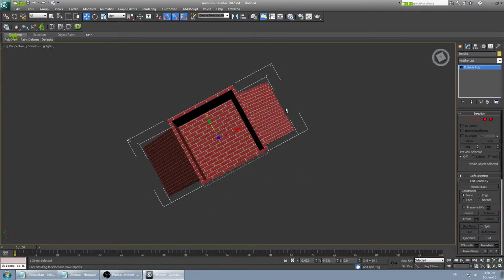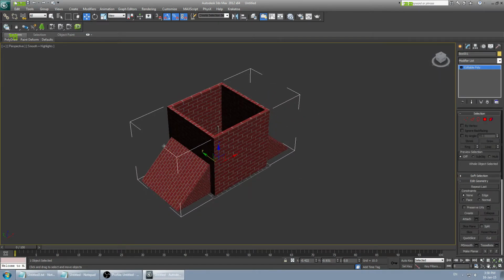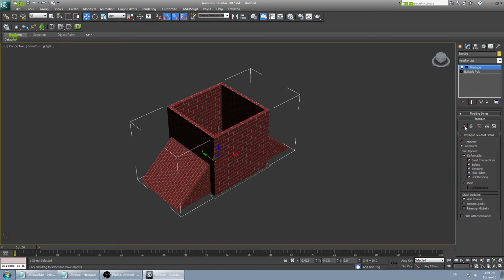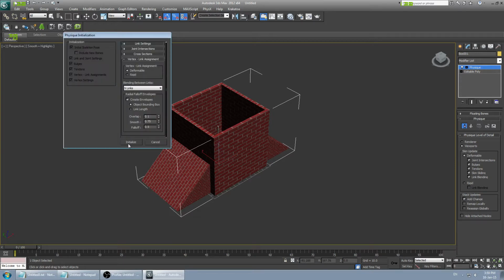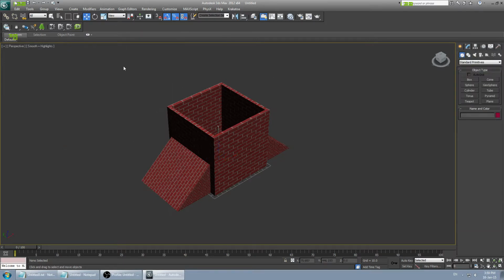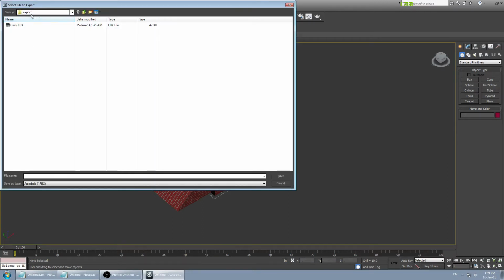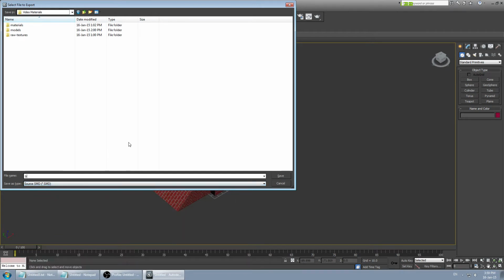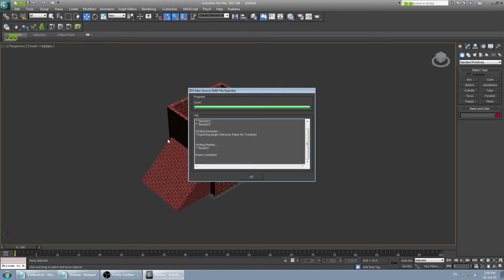And now we need to attach all this mesh to a bone. For this, you go into modify, click the list, and find Physique. This one, not anything else, but Physique. Then click attach to node. It's the small guy with the target on him. Click on the bone and initialize. That's it, that's finished. So we can export this. Call it box body, so I know the difference.